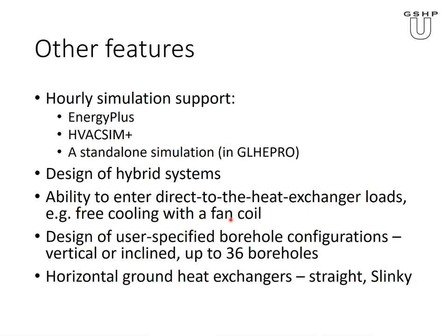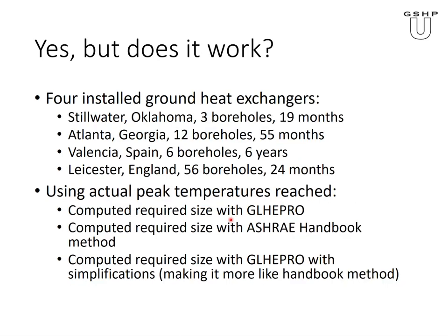You can make the boreholes vertical or inclined. They can even be different depths, although I would say the simulation doesn't take that into account in every respect. It doesn't have any way to recognize that if you have different depths of boreholes, they may have different flows. It's not that sophisticated. We can model horizontal ground heat exchangers, straight in-a-line heat exchangers or slinky heat exchangers. So it has quite a few features.